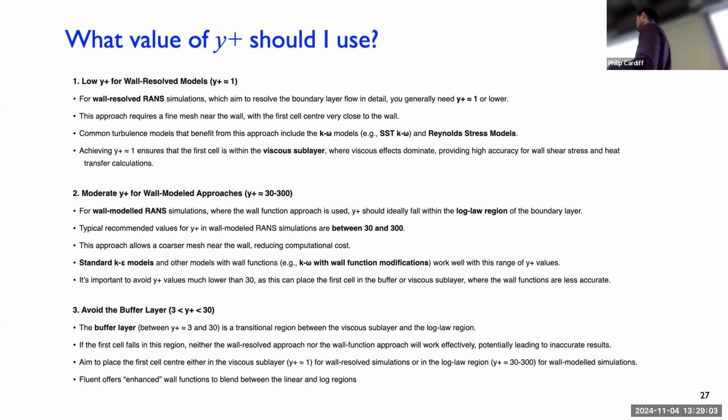and you're not properly modeling it with a wall function. And so you might ask me, this sounds like a real pain. How do I know in advance what the y plus will be? You can estimate it based on experience, but typically what you'll do is you will set up your simulation with a best guess, run it, get the velocity field, and then in Fluent and OpenFOAM, you can look at a y plus field. On the boundary, you look at the y plus field after solving it.